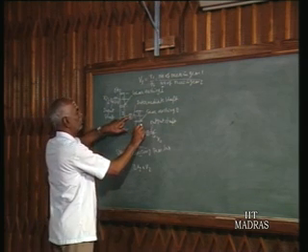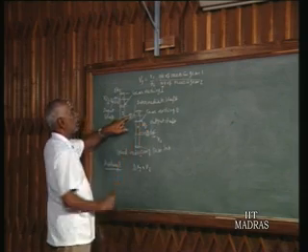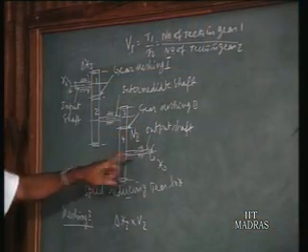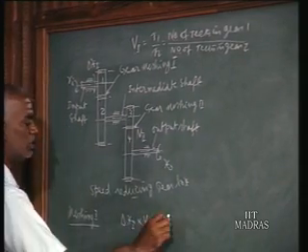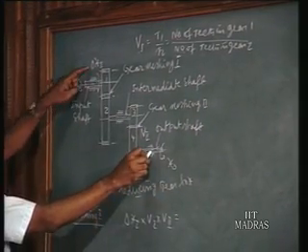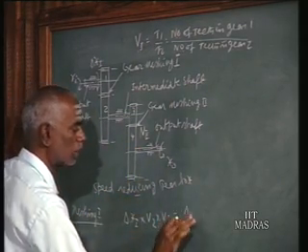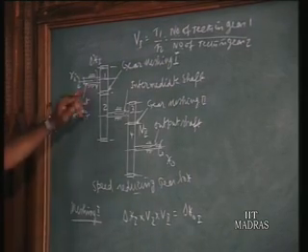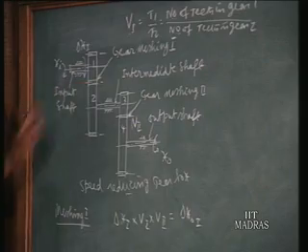Similarly, if V2 is the velocity ratio at the gear machine 2, then this much motion at the intermediate shaft, at the output shaft, will be equal to delta x1 into V1 into V2. So this is the equivalent motion of delta x1 at the output shaft. I will say delta xo1. That is, we are finding out what is the error in the output signal due to a backlash of delta x1 at the gear machine 1.